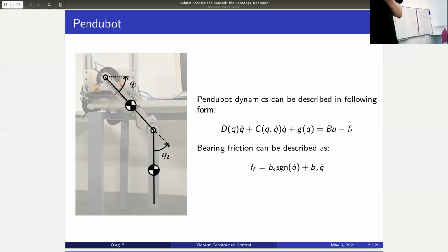And the second approach is a cost function approach, which LQR uses, where you define your cost based on some integral of a very simple quadratic cost. That does not involve overshoot. You cannot control overshoot directly with it. Correct me if I'm wrong. You can do it indirectly, but if your function has a very tiny spike, then goes way down. Of course, for linear systems it is all simpler, but whatever.